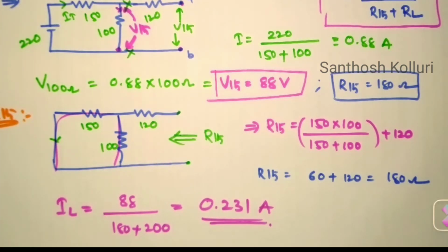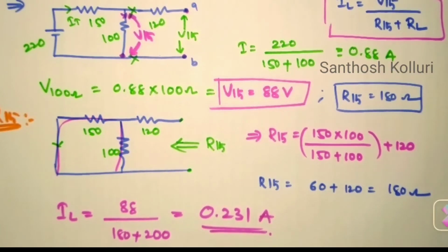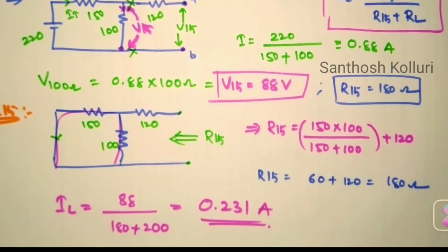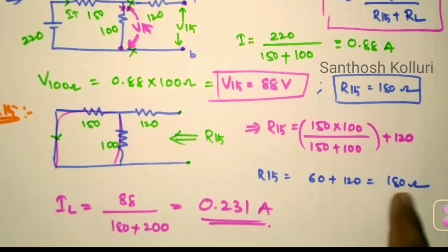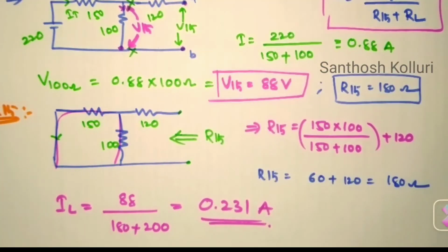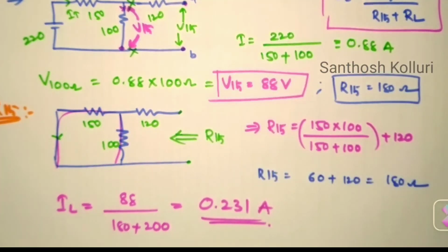So here this is the Thevenin's theorem, and in the Norton's theorem the calculation of RTH is the same. So there we'll take the RTH value as 180 ohms. And here we need to calculate the Norton's current from the same circuit. We'll see now.